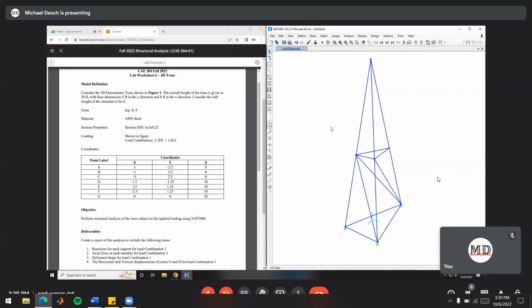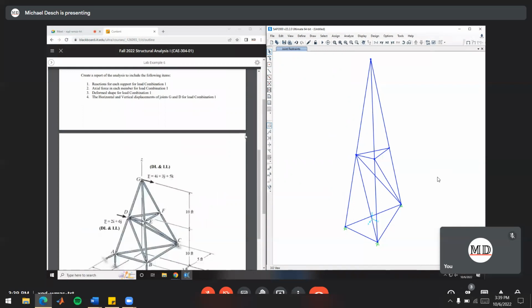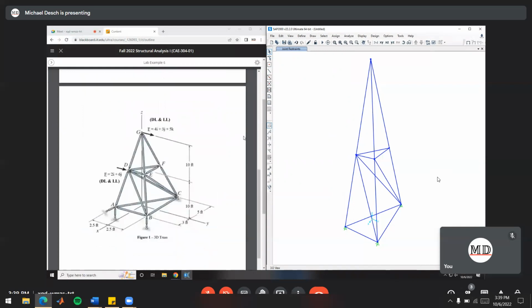Awesome. Okay, so last thing we need to do is actually put in our loads now that the background for them is set up. We're going to have 2 point loads on the structure. So if you recall, that's another unique thing about trusses. They're only loaded at the joints and not on the members themselves. I mean, in reality, they can be, but on a perfect theoretical truss, we only want them to be loaded at the joints here. Otherwise, you're going to get bending and stuff in the members, and it's going to turn out different than the equilibrium equations will tell you.